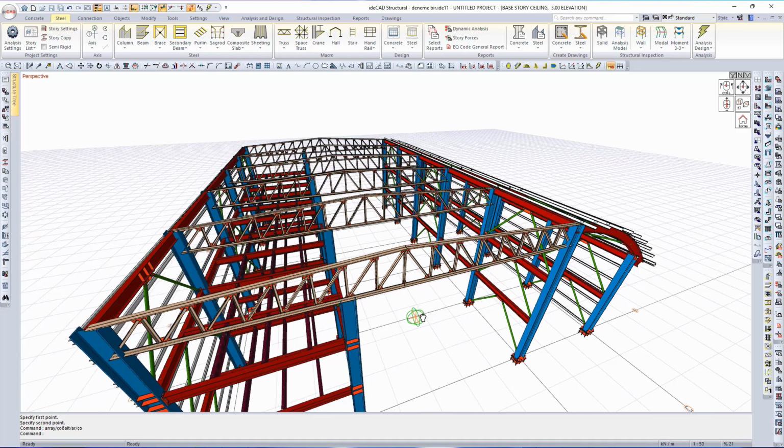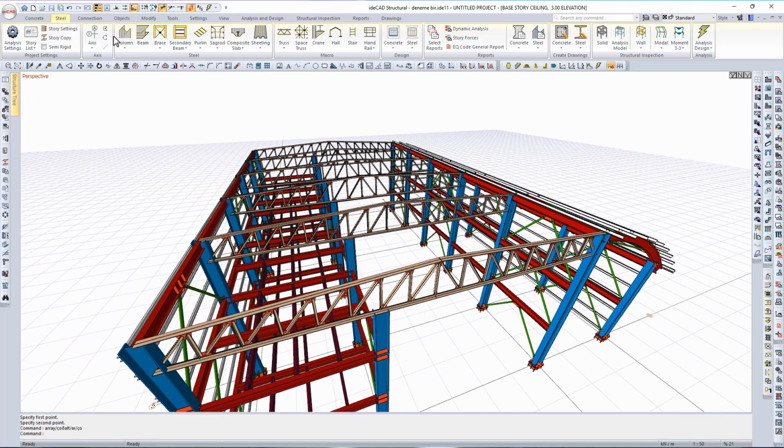Trusses have special considerations when it comes to purlins and bracings. To prevent bending moments or unintended forces on the chords, members are only allowed to be connected at the node points of the truss. No elements can be placed between nodes. At the first and last node points, you can either apply an offset or choose to remove these elements to avoid clashes. Let me show this with the multiple elements brace command.